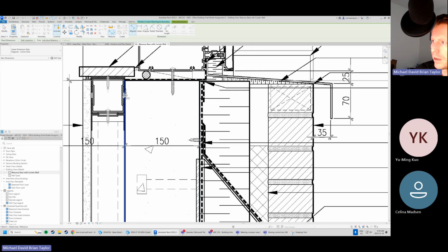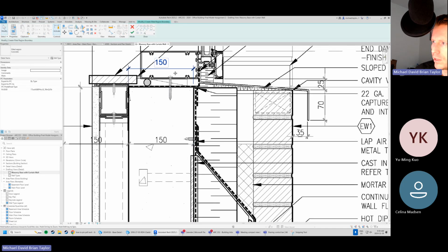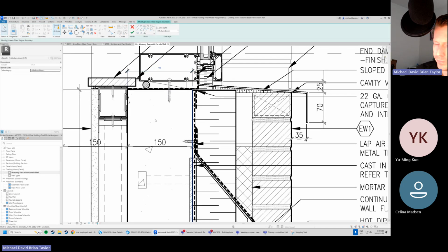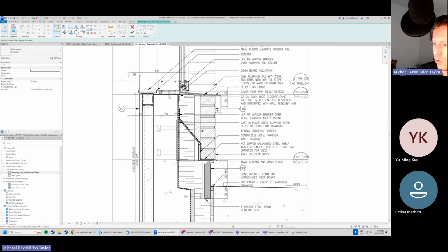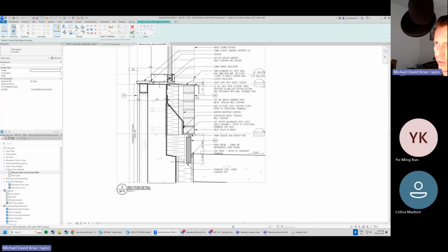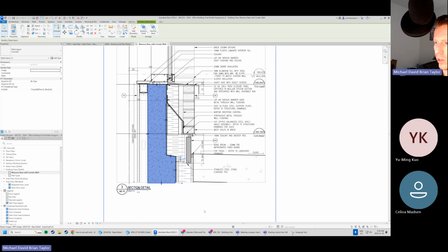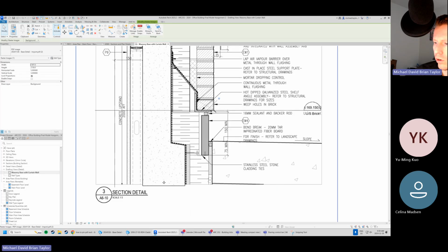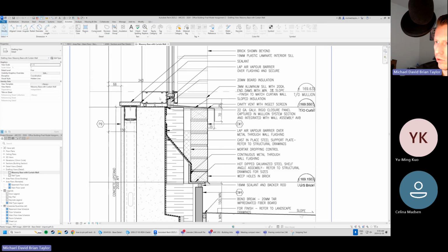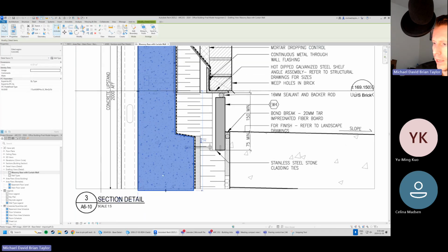I'm dimensioning right now the filled region. So remember, we're still inside of the filled region tool. We can tell that because we've got this little check mark here and the X. Your filled regions have to be closed loops. So if I hit that check mark here, wonderful, right? So you can see here we've got our concrete. Concrete's done.